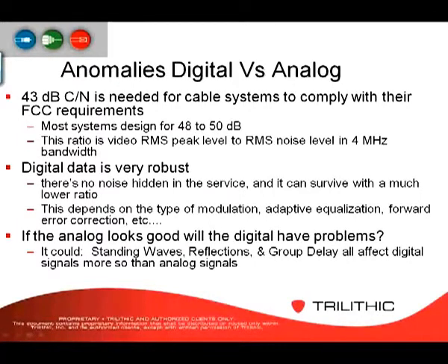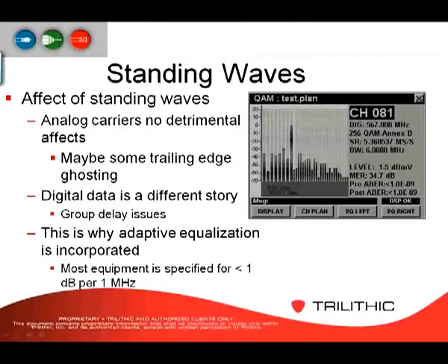At best, with an analog signal, the picture quality could look pretty good from a noise or distortion standpoint, but in an analog environment, when you have reflections on an image, it would look like a double image, or what we call ghosting out in the field. So the effects of standing waves on analog carriers are really not detrimental, other than, like we said, the trailing edge ghosting.